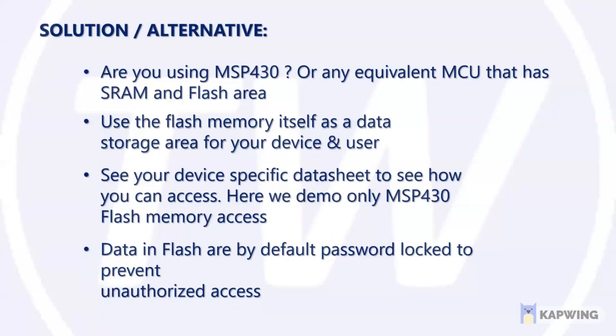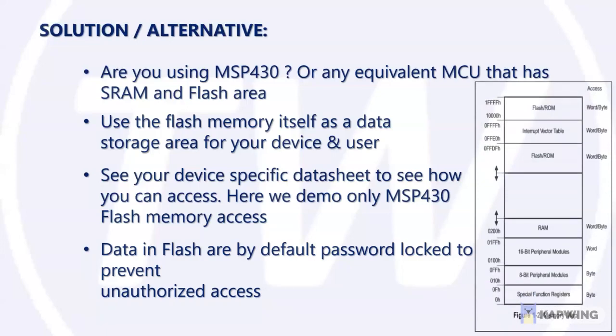Also, after a certain interval of writing, you have to lock your flash memory area. That's simply because the flash memory inside the MCU has a limited writing exposure time. So this is something that you might want to look into. Just refer to your device datasheet. There is a particular restriction in timing through which the flash is stressed to the higher programming voltage. So you can't just keep on writing the data and keep the flash writer process on. You need to turn it on, write the data, and turn it off. Apart from that, everything is very easy.